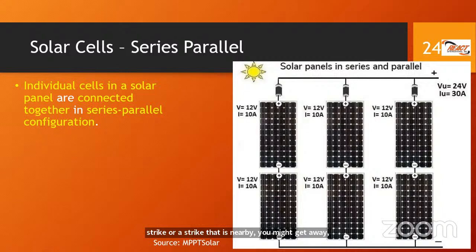Some hams, what they do when there's a lightning storm around, will disconnect the coax and put it outside the shack, so that it doesn't come into, connected to your equipment. You disconnect it. But you cannot always be home when there's a lightning storm around, right? So grounding and bonding is critical, and also using things like polyphasers that will essentially shunt that discharge to ground